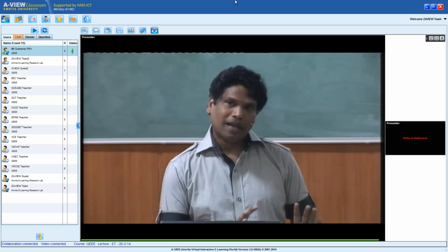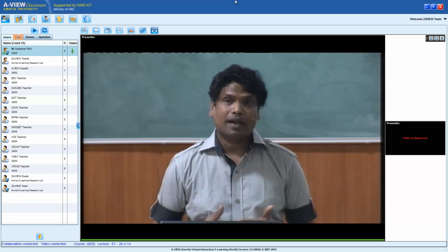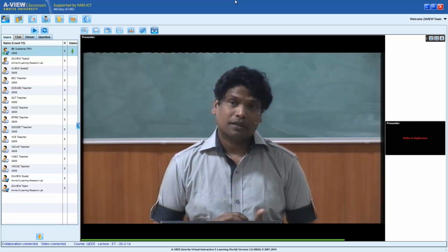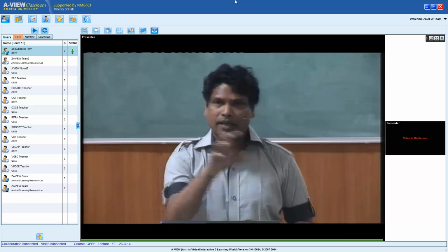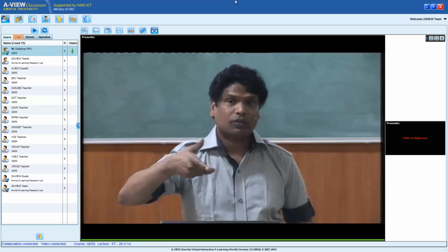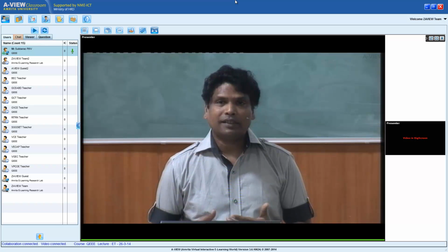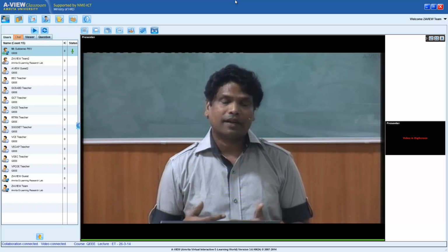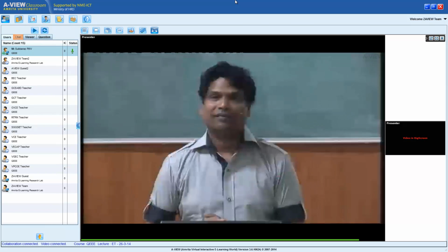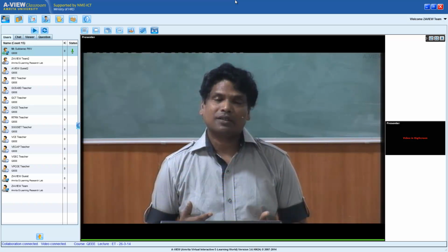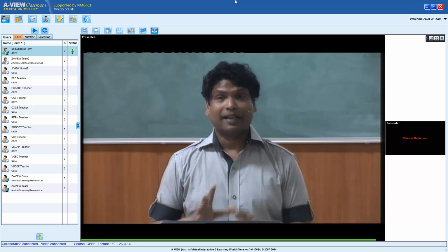If I take monoatomic gas and polyatomic gas at the same temperature, the polyatomic gas will have more random motions, meaning more degrees of freedom: XYZ, rotating about the x-axis, rotating about the y-axis. Each motion demands some energy. So whenever the number of possible motions, the degrees of freedom, is high, I have to feed each degree of freedom some energy to get a temperature change. Explicitly I am wasting my resource on this fellow to give unnecessary motions. This is the microscopic kinetic energy part.